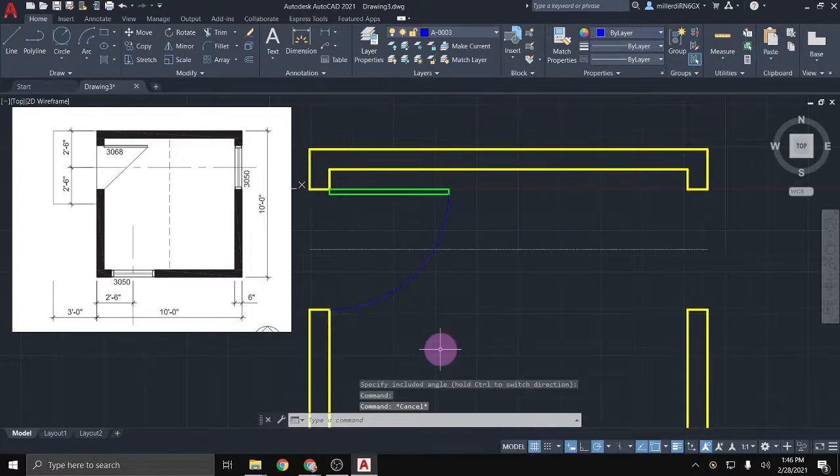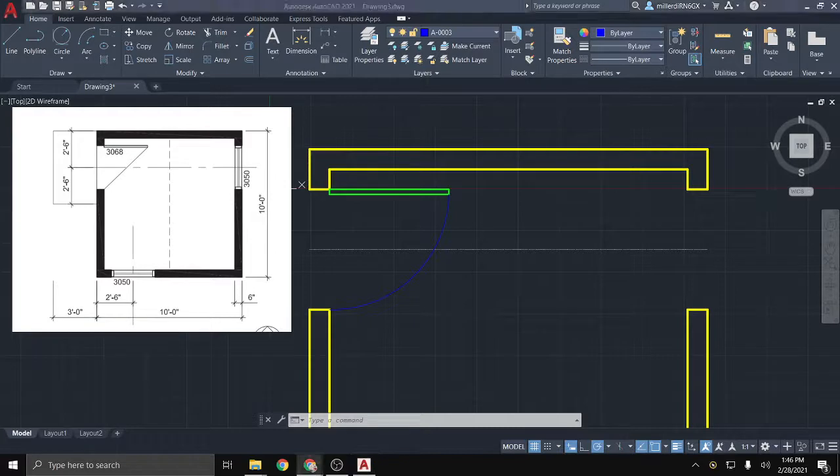We'll go over something too called blocks, in which we can get these reusable pieces of content and just plop them in our drawings to make things nice and easier, so you can just find a door and download it and put it in your drawing, and no one will be the wiser. Okay.